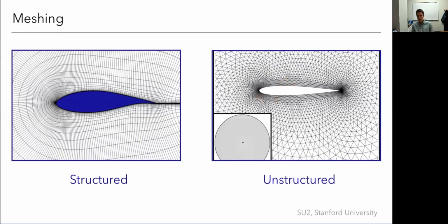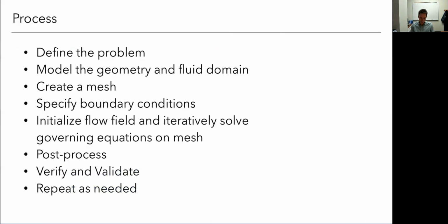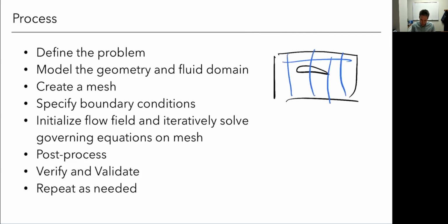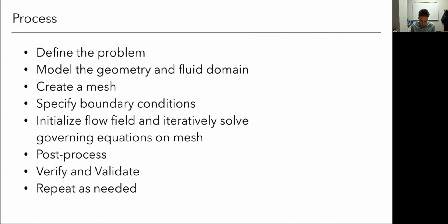And so we'll do things like mesh refinement studies. Those are absolutely critical. You never want to show any results without doing a mesh refinement. And that means I take all my cells and I divide them. In the ideal case, this is totally impractical, but just to say, let me draw this ridiculously coarse mesh because I don't want to spend all day drawing a mesh. I would take every cell and I would divide it up. So in 3D, maybe I divide it into 8 things, or whatever. And I'm ignoring the geometry here just to make my life easy. I'm not meshing around it. That's totally impractical because that's going to balloon my cells very quickly. But what I do is I try to refine around areas of interest as much as I can.